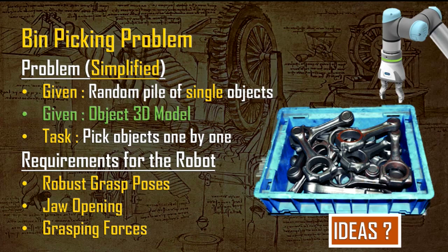That's a very good point, and I would want to add here. Your question is exactly valid: how you can capture the position as the objects are picked again and again. As already discussed, one of the best solutions from the industry front is to have a 3D depth camera. You will use machine learning and computer vision algorithms to identify the object position with respect to the 3D world, not just the 2D world, and it can also give you the orientation.